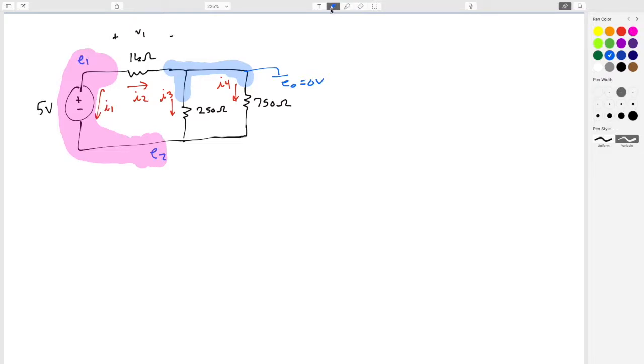The neat thing about this is that now we just have a ground node, which we know is 0, and then one node, and we can generate the equation we want just on that supernode. Inside of that supernode, it's saying what? E1 equals E2 plus 5 volts. Then we come up with a KCL equation, a node equation, for the entire supernode using other terms. For example, this current up here, indicated by I2, would be E1 minus E0, or 0 volts, over 1 kiloohm. So that's that one. Are there any other currents flowing out of this node?